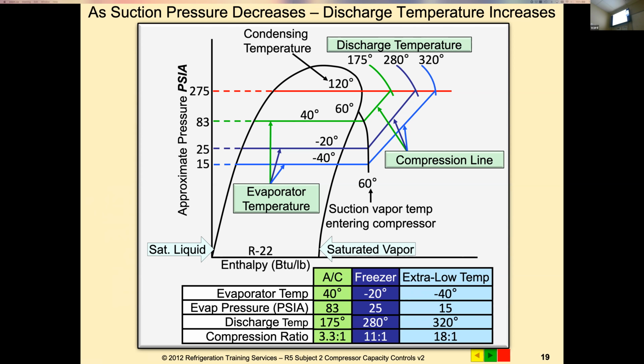Yeah, so this is just an enthalpy chart. These are available to you when you buy refrigerant. It's on the back of a lot of the cases. It's in a lot of charts that we throw away with our parts. If you're dealing with the refrigerant circuit and you need to know enthalpy, it's important that you understand it, because if you do a retrofit, you're going to need to know how that changes: how it changes your compression ratio, your mass flow, and your interaction with the oil in the system. So you need to know those couple things.